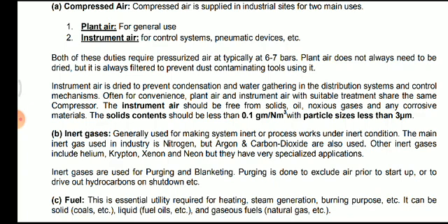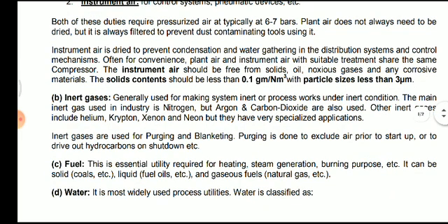Instrument air is dried to prevent condensation and water gathering in the distribution system and control mechanism. Often for convenience, plant air and instrument air, with suitable treatment, share the same compressor.